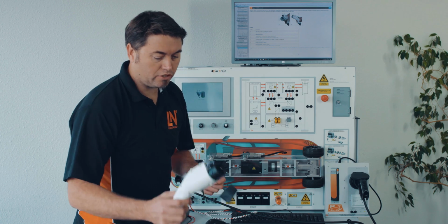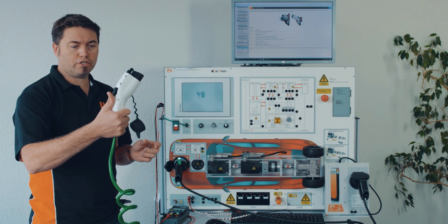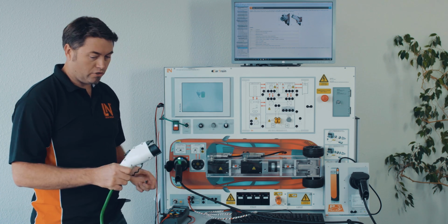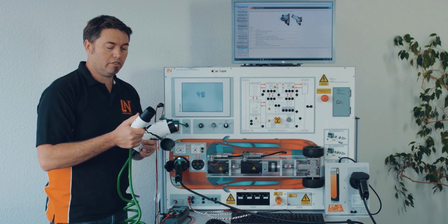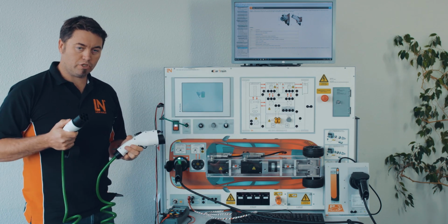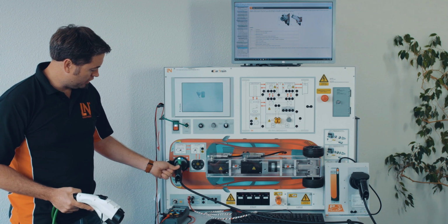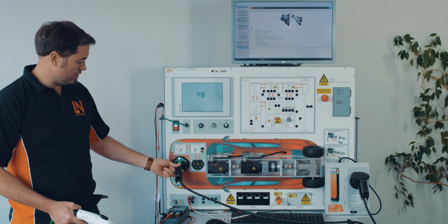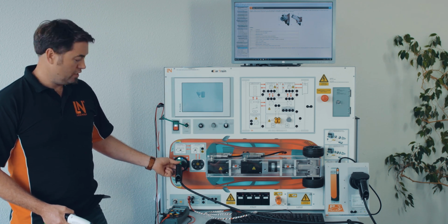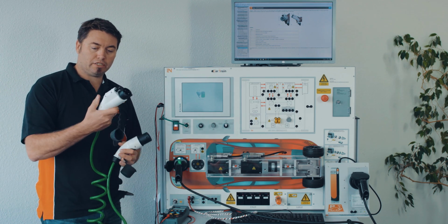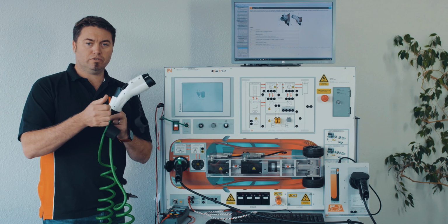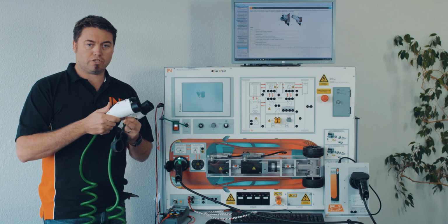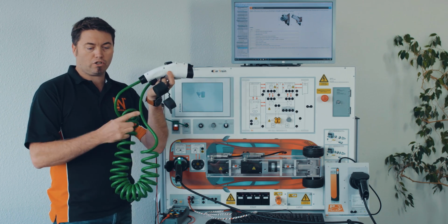Because the type 1 connector that you see here has a switch, there's no need to lock the vehicle. But in a lot of the European countries, you can see that there is no switch on the connector. So basically, if there was no switch, you could pull it out. So this system is now locked in. It happens when I've turned the vehicle off and even locked the vehicle. Once those conditions are met, the system is locked in there. With the type 1 connector, there's a switch inside. So when I press the switch to undo the mechanical lock, it also shuts the charging off. So there's no need to lock the vehicle in this instance.